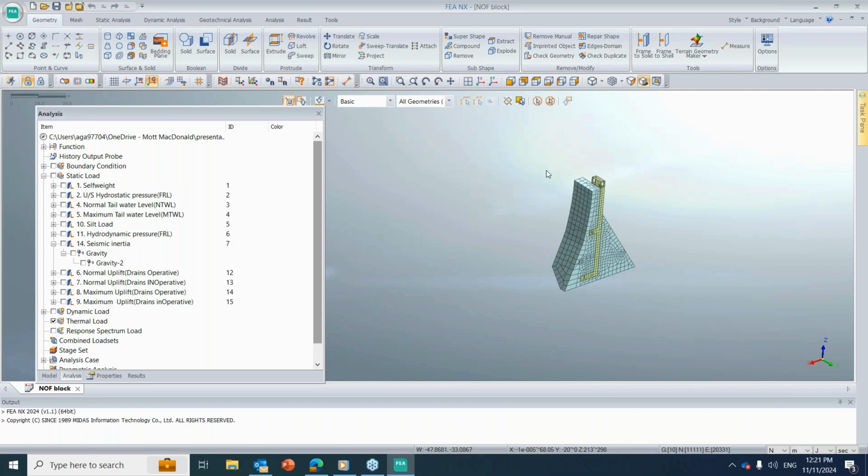But it all depends on the material. If your prominent deformation bulb exceeds that, then you may have to increase your model boundaries. But if you are using free-field boundary elements or absorbing boundary elements, that much extent, the height of the dam, should work fine in normal cases. But you have to check the deformation bulb after the analysis.